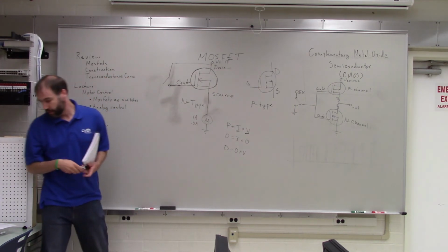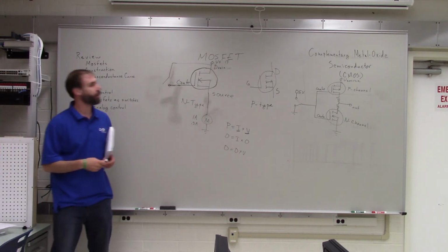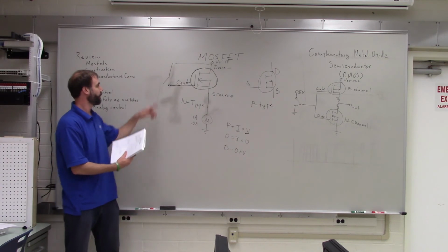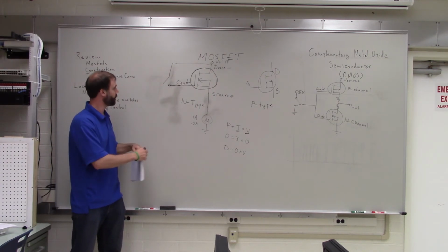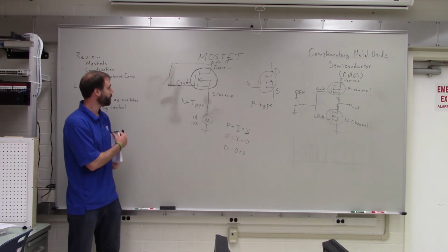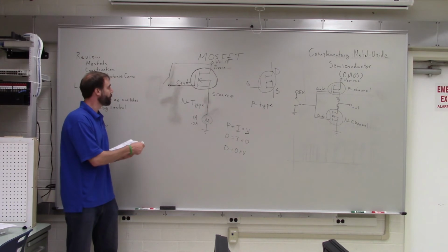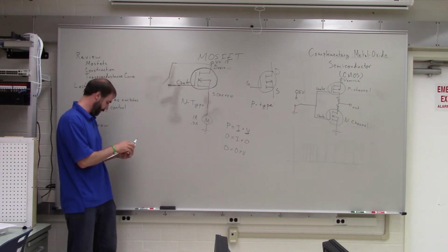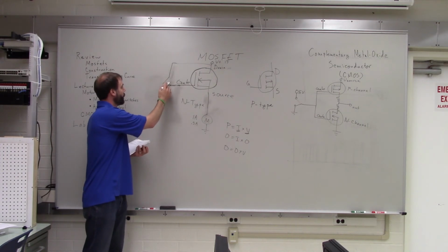We've actually got little motors here, so every group is going to grab a motor, and then you'll be able to turn them on and off using the MOSFET. So one side of the switch is going to power, and the other side of the switch is going to ground. So really the switch is more like this.